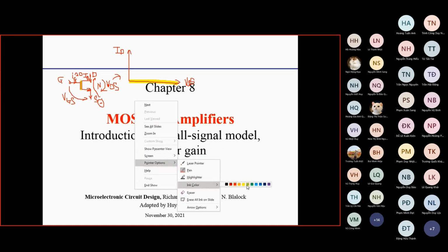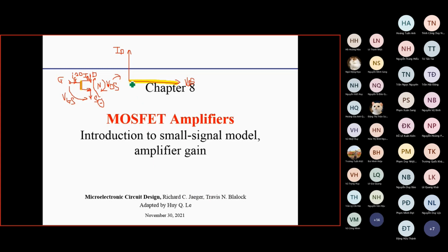Okay. So when you increase VGS, the input voltage, so that it becomes higher than the threshold voltage, then you can attract electron minority charge from the body to create the channel here that connects the drain and the source. And if you apply a positive voltage VDS between the drain and the source, then an electrical field will accelerate electrons from the source to the drain. That means you create a current running from the drain to the source, right?